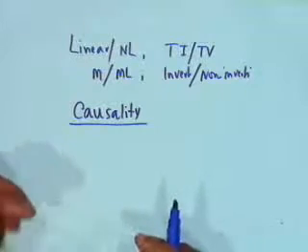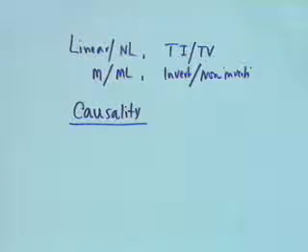Causal or non-causal. And for characterizing a causal or non-causal system, all we do is appeal to common sense. And the common sense is this. Our purpose is to show that h of n is still a characteristic. It still characterizes causality, causal or non-causal system. H of n or h of t, as the case may be. So we appeal to common sense. We say, suppose the system receives a delta t. Alright. Now, can the output appear before delta t shows its existence? Delta t is the input, the output is h of t. Can h of t be non-zero before t equal to 0?